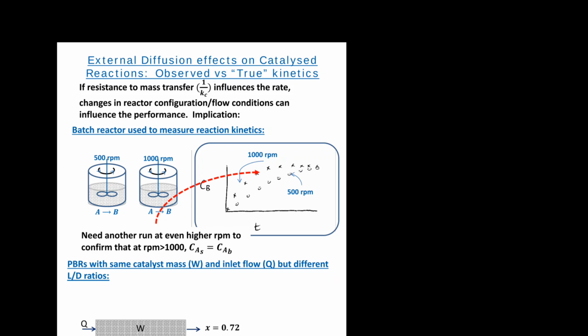When you do experiments to determine the reaction rate or the kinetics of a specific reaction, it is very important to show to yourself and to other readers that you thought about external diffusion and that you eliminated its effect on your reaction rate. External diffusion is a reactor-specific parameter, and you cannot use data that was generated while it was present in a different reactor system.